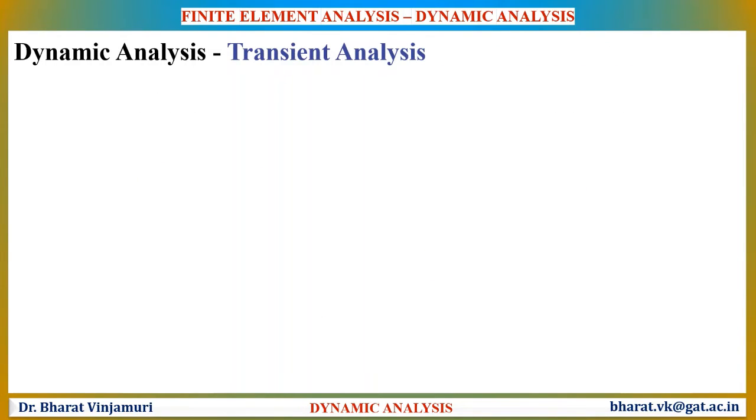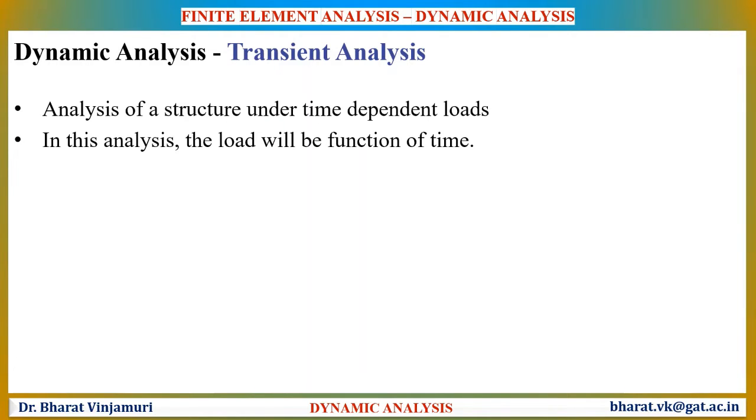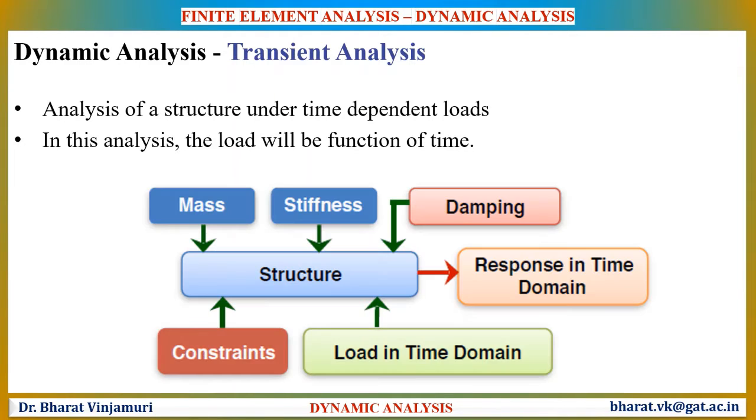The next type of dynamic analysis is transient analysis. It is the analysis of a structure under time-dependent loads. In this analysis, the load will be a function of time. So clearly, the main objective of this analysis is to determine the response of the structure within a time domain. In this case, the load will be a function of time and the effect of load will be considered during the analysis.